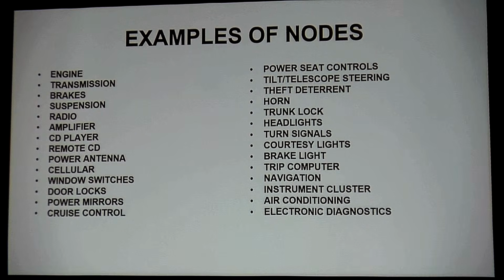So we've got to all start to realize what system you're going to work on when you're having a problem. Remember the problem: I requested a switch, and the switch only made a request that was carried out by a task in the micro. Now this starts to change everything. So if I'm trying to put a wiper on, is the wiper going to be on the high-speed bus? No. So if you had a multi-connection going into the steering column where you had high-speed wires coming in, those aren't for the wipers, guys. That's for the steering angle sensor, because for the steering angle sensor, I need speed.